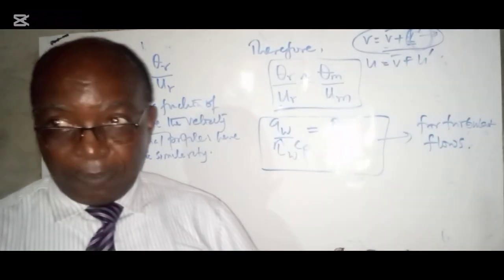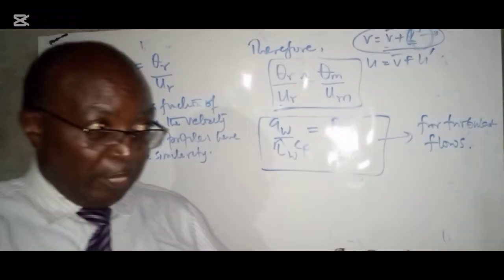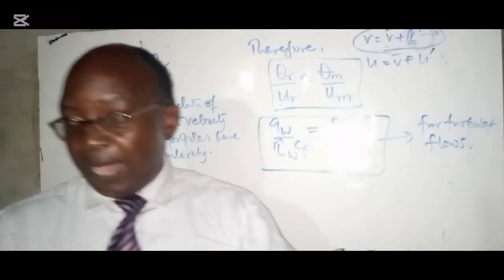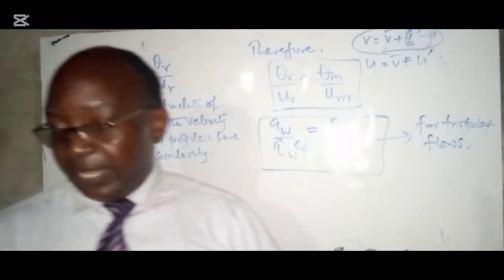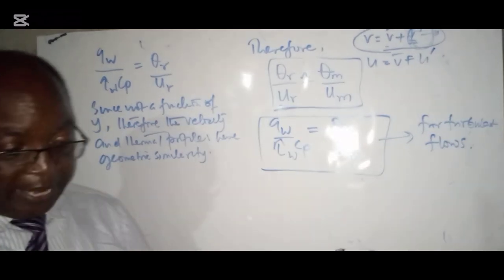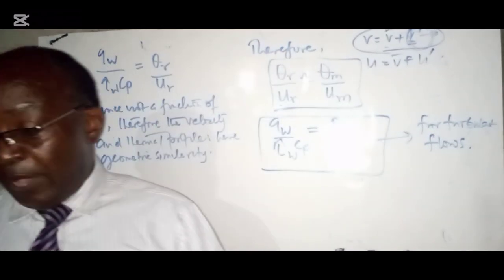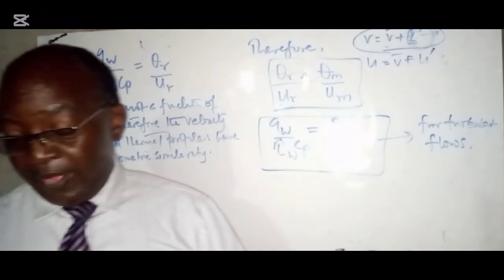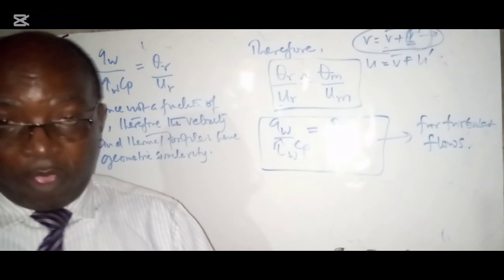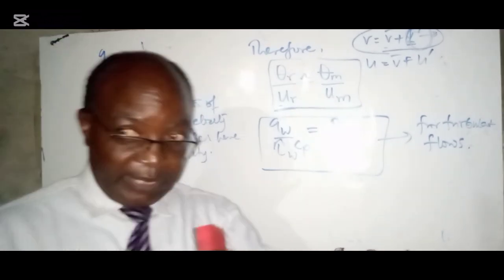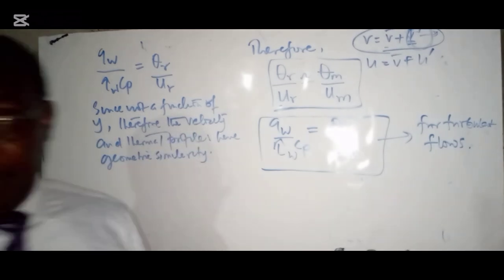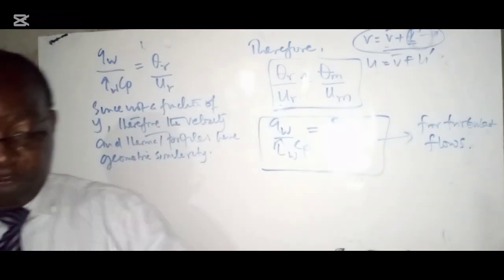In addition, we built up the system so that the Nusselt number is expressed as a function of the Reynolds number and the Prandtl number. We know the assumption involving the Prandtl number, where the thickness of the velocity boundary and that of the thermal boundary are the same, meaning the Prandtl number is 1, and we came up with several expressions.